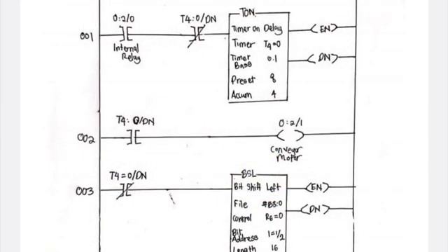The PLC program for bottle capping is as follows. Based on the PLC ladder diagram, rung 001 and rung 002 are used to operate the conveyor motor. Assuming it takes 0.5 seconds to cap a bottle, capping is performed when the conveyor is stopped for a second. When push button input 1/0 is closed, it will energize the internal relay. Then conveyor motor output 2/1 runs for a moment and stops for a second. Then the timer is in auto reset mode by T4:0/DN in series to it.